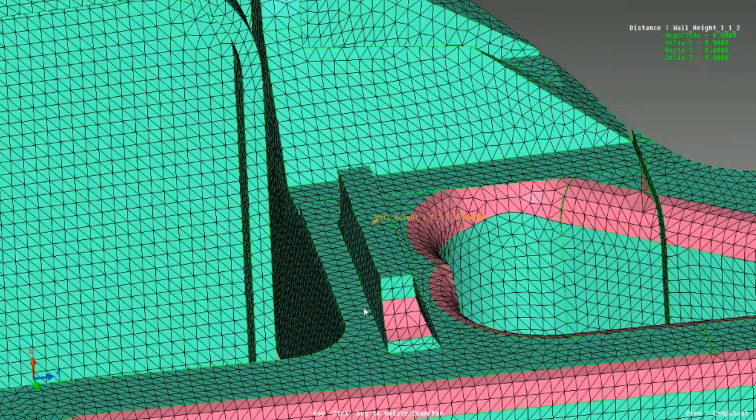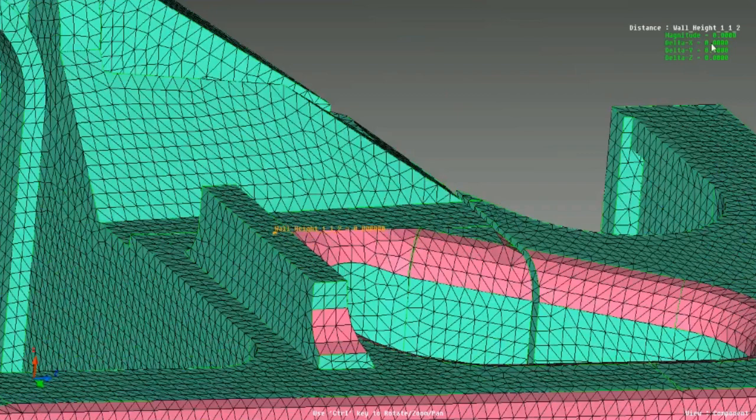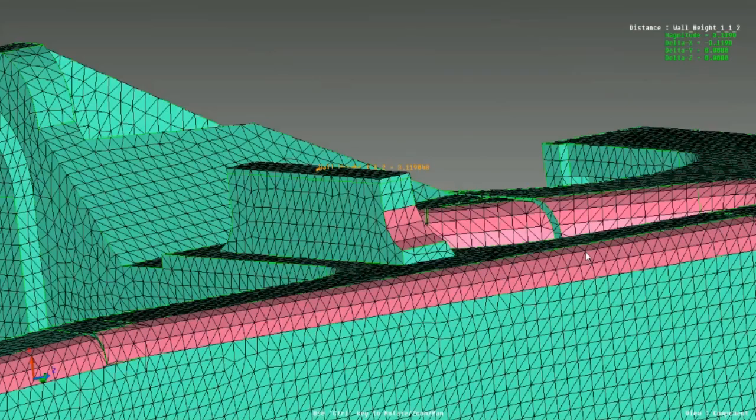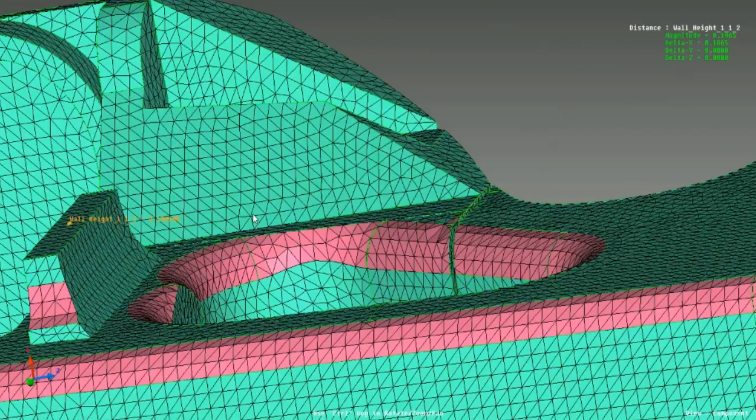And we also have some sensors. Once we link the parameter that I just created, before making the change we see that the value is 0 on the sensor. As we morph this rib height in real time with the help of this sensor, you see this value is changing, and it helps us understand to what extent we are morphing. This tool comes in very handy if the user, while defining the parameter itself, wants to understand to what extent he can morph, and based on that he can make the necessary changes.